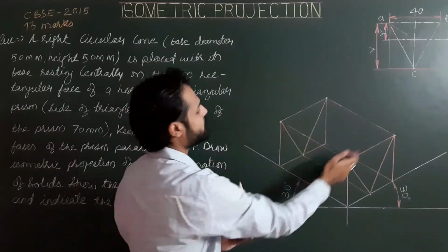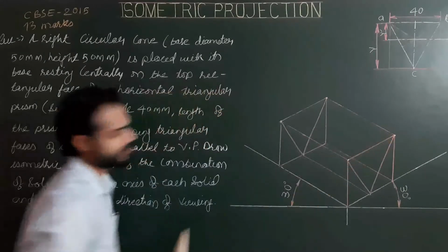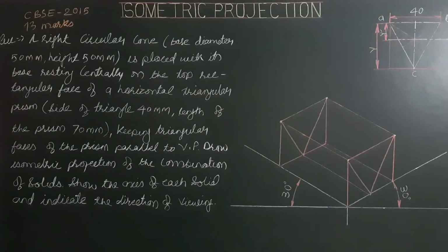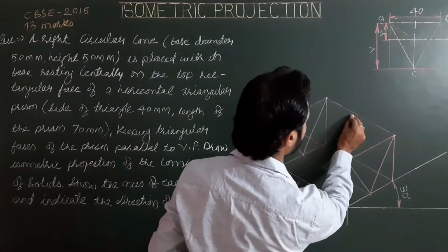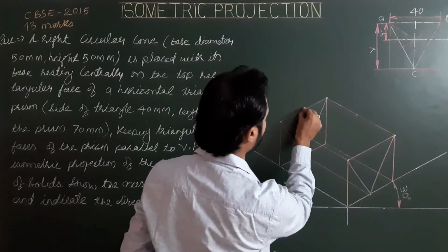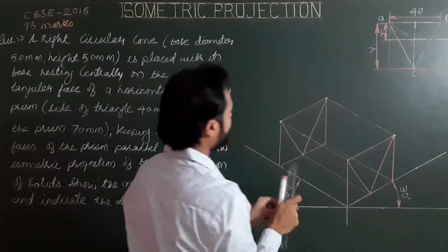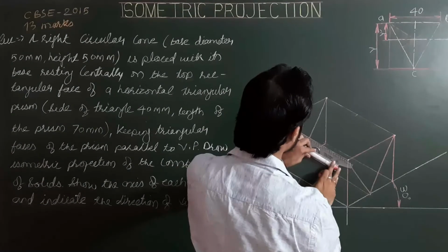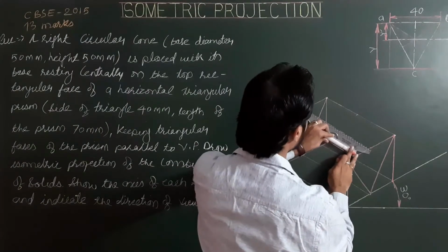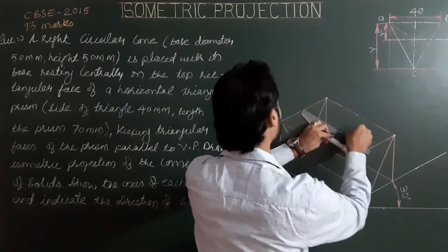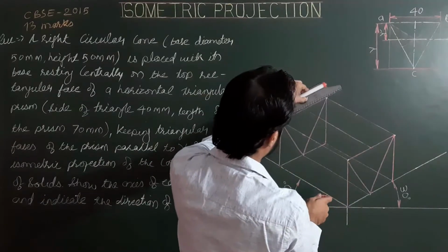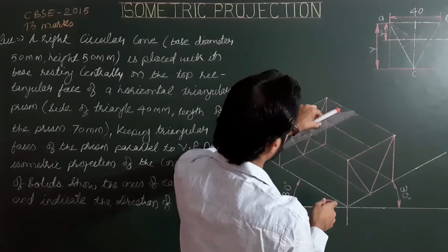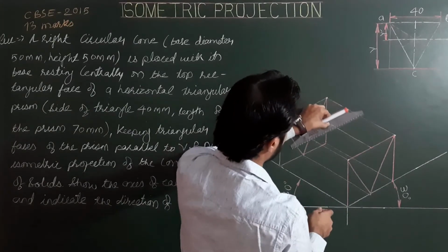So first we have to find the center of this upper rectangular face, by setting all four sides of the upper face, and then drawing lines parallel to extreme sides, or parallel to first and second ISO axis, the center lines.